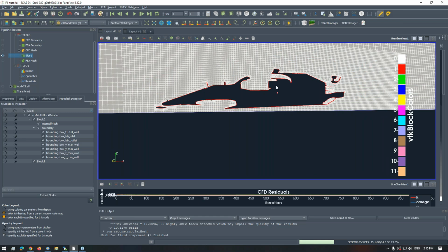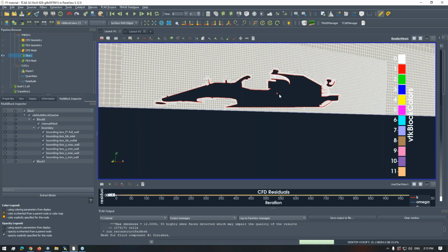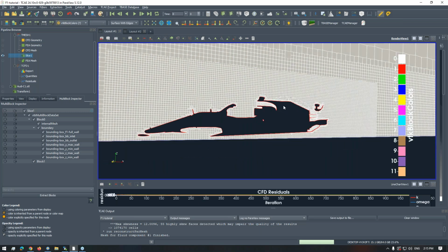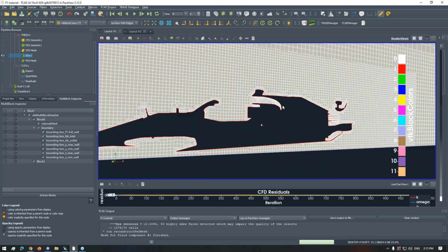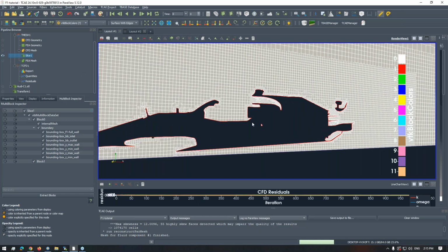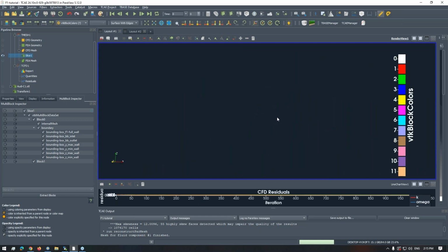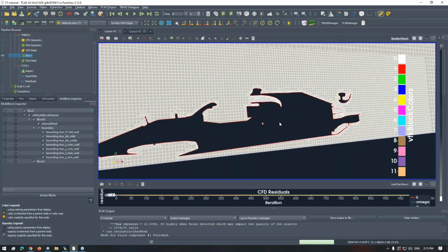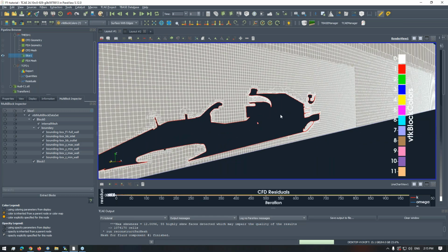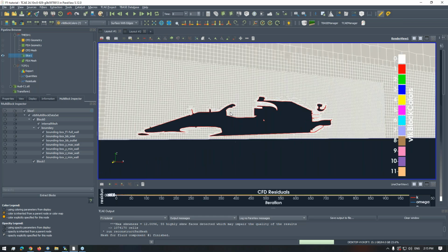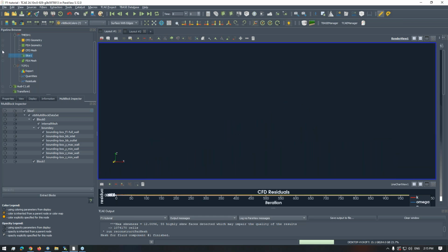Because if you put water in it, the water should stay in it. There should be no holes. Otherwise, when you are meshing the model, the mesh would be created from the inside, which is certainly something you do not wish, because it's a waste of computational power, if not accuracy and stability. But yes, you need a waterproof model.